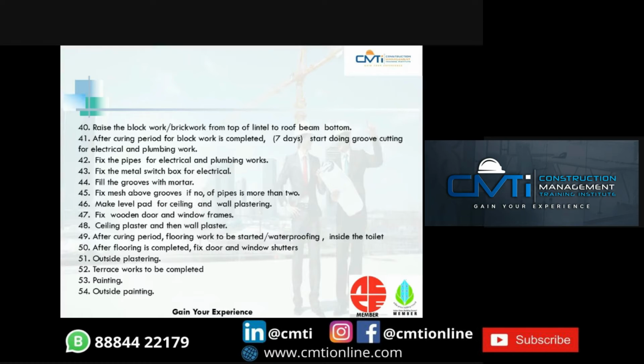Fix all the wooden door and window frames, and ceiling plaster, and then wall plaster takes place. After curing period, flooring work is to be started, waterproofing inside the toilet, and after the flooring is completed, fix the door and window shutters. And after doing this, you have to start the outside plastering, and the terrace work has to be completed, and the interior painting is done, and lastly the outside painting is done.